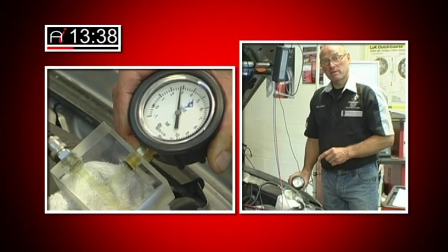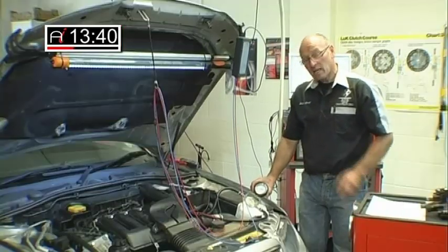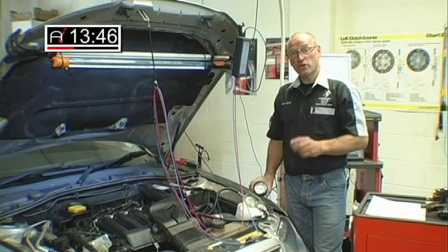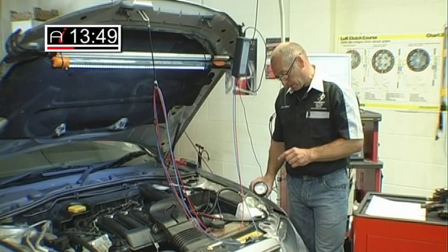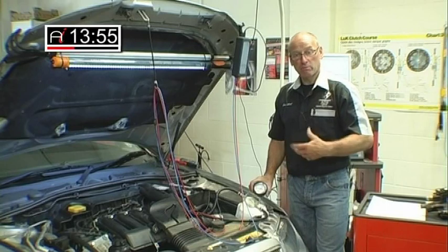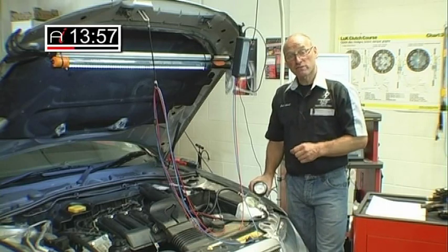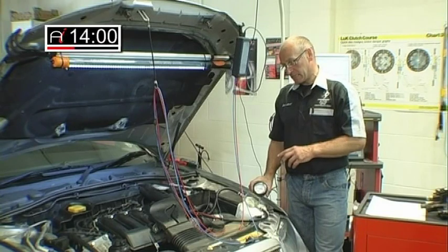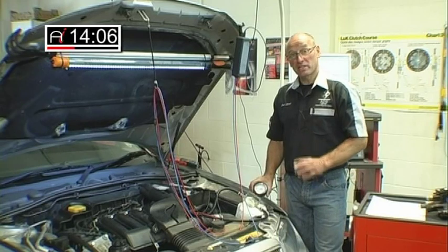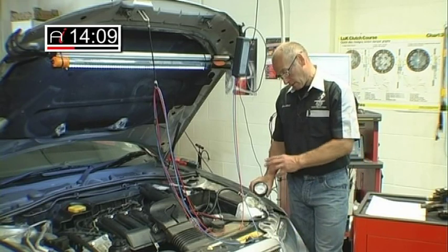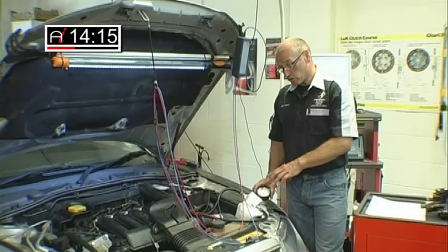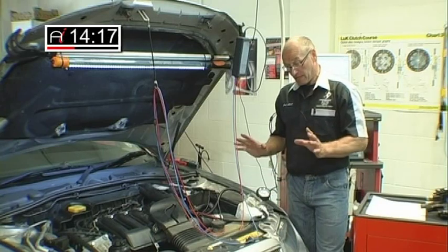If you can turn off, please. If I did have a problem with that pressure, the next course of action would be to check the current flow through the pump, because I then want to prove, is this a problem with the pump or the actual hydraulic circuit, in other words, the pipework, blocked filter or whatever. And by monitoring current flow through the pump, that also helps me predict whether it's a pump fault or not. But at the moment, I can't fault it, so there's no point in me doing any checks with regards to current through the pump. So that part of the test for now is finished. I'm leaving the gauge attached, so I keep my eye on that at all times while we're doing other further testing. But apart from that, that test is finished.